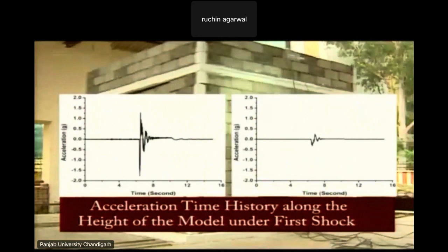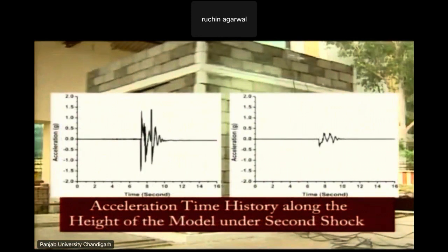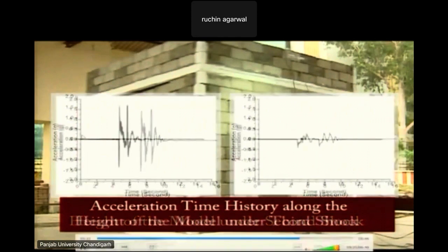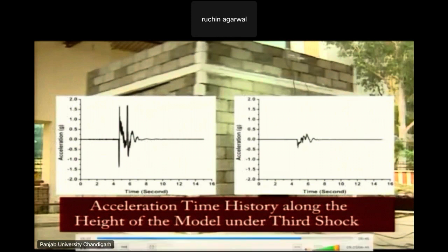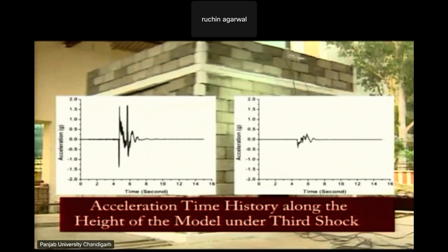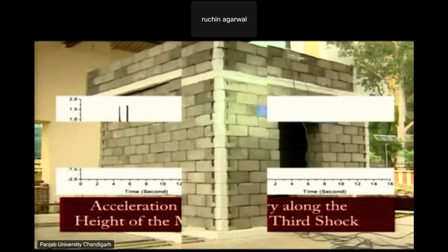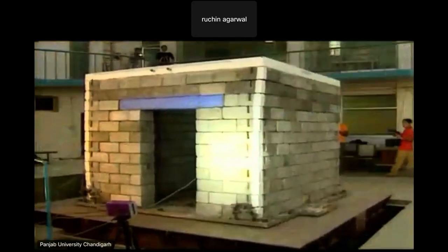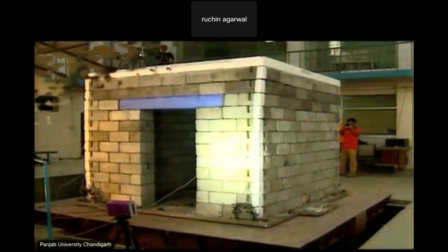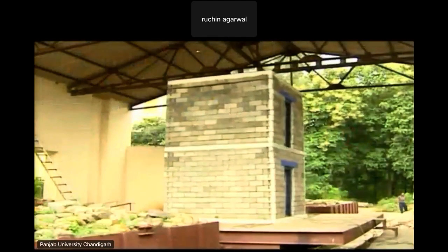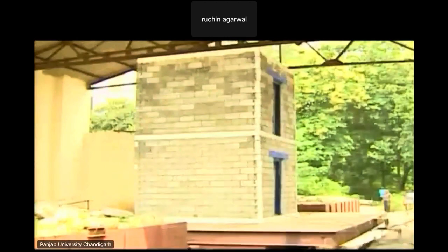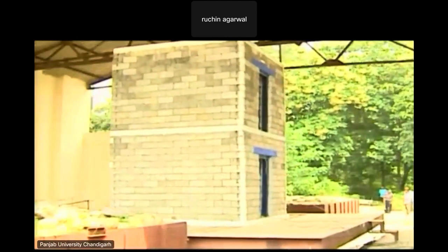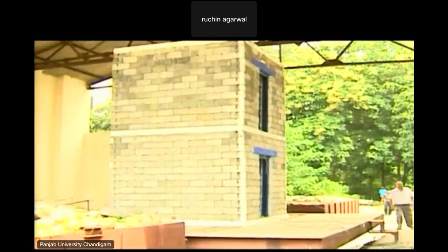In the test results, it is seen that peak acceleration at the roof of the model is significantly lower than at the base of the model, without any distress or damage in the model. It underlines the complete energy dissipation through viscoelastic links without damaging the blocks. The elastic plastic behavior of viscoelastic links reveals that the model regains its original position after completely dissipating the energy imparted during the shock test.